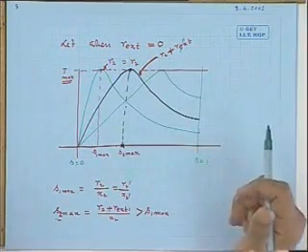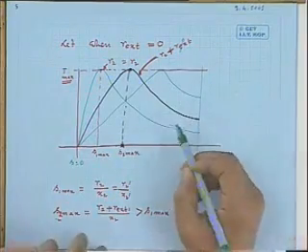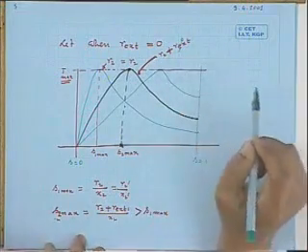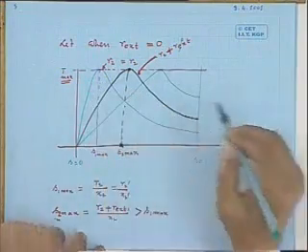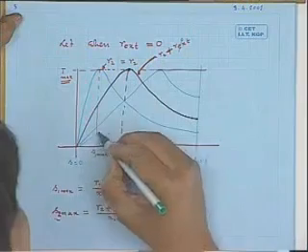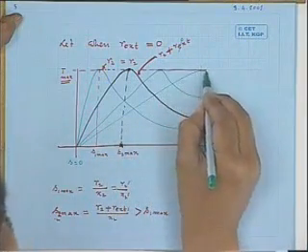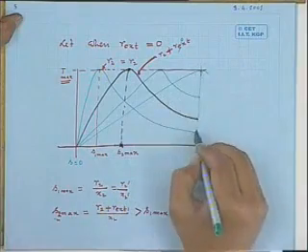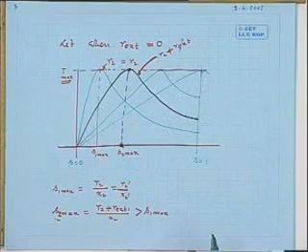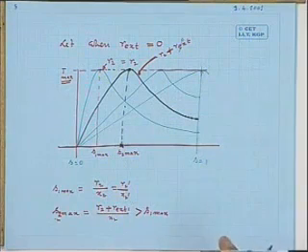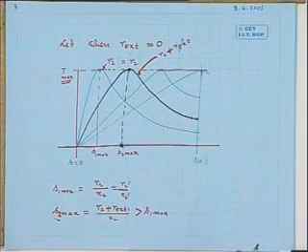Starting torque increases. The value of the starting torque increases. In fact, one can choose some optimum value of R external such that whatever maximum torque the machine can develop will appear during starting. That is, you choose your external resistance in such a way that your maximum torque occurs right at S equal to 1. See, simply by connecting resistance in the rotor circuit.